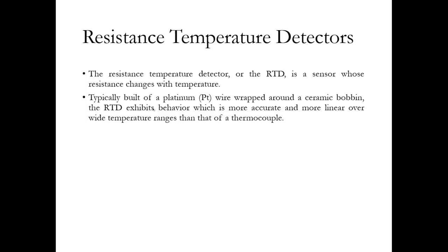So another one is thermocouple, where we have two dissimilar metals actually being combined. We'll talk about that later on. But this is just to give a difference between the two, and why sometimes RTDs are preferred. Because RTDs are part of the resistance change, we have classified them into the variable resistance type of sensors. Because we have a platinum wire wrapped around a ceramic bobbin, and platinum has a well-defined temperature-resistance relation, more of a linear relationship between the temperature and the resistance.